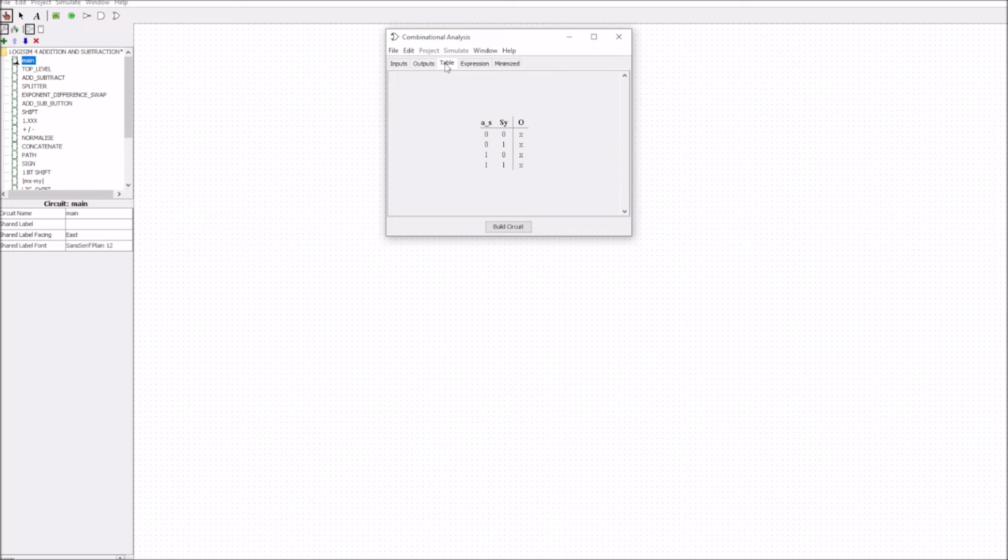And then we can go to the truth table. So we're going to have the truth table here. We're going to have 0, which means addition, and 1, which means subtraction. And the value for the sign for y is either going to be 0 for a positive value or 1 for a negative value. So whenever the sign of y is 0 and we're going to do addition, we just leave that at a value of 0. Whenever the sign of y is 1 and we're going to do addition, again we leave that a value of 1.